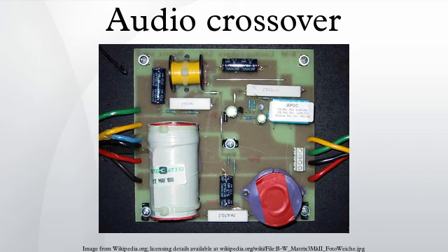They can be designed and built so that they have a linear phase response, which is thought desirable by many involved in sound reproduction. There are drawbacks though. In order to achieve linear phase response, a longer delay time is incurred than would be necessary with an IIR or minimum phase FIR filters. IIR filters, which are by nature recursive, have the drawback that if not carefully designed they may enter limit cycles resulting in non-linear distortion.